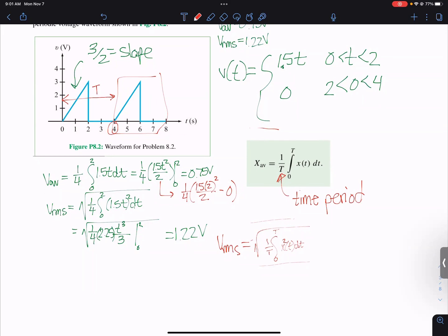The other thing is, if you look at the average of the power coming out of a wall, that is a sinusoid, so your average is going to be 0. So if you look at the average there, you're like, well, it's not 0. That's why we're looking at this for AC. It really has some value to it. And that's where the RMS comes into play, because it's an AC signal that I can now represent and actually get a value for what power is going to be consumed. Does that help? It does.